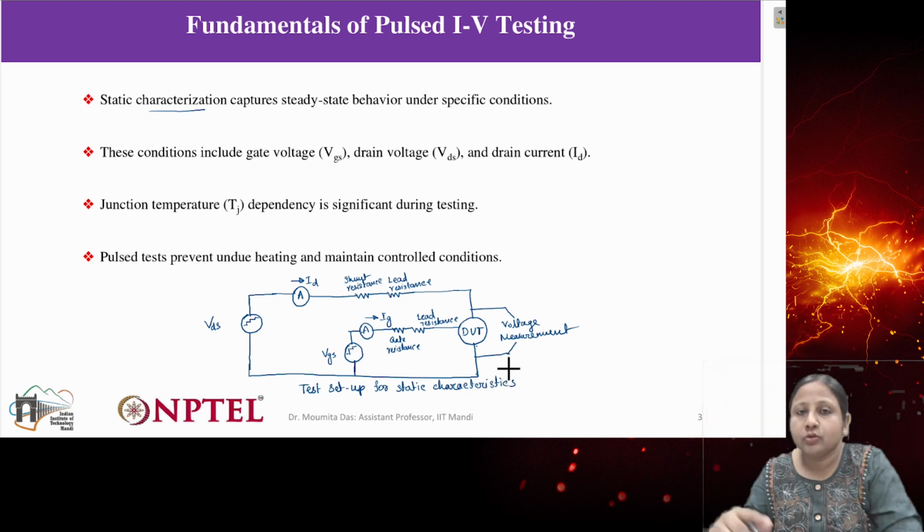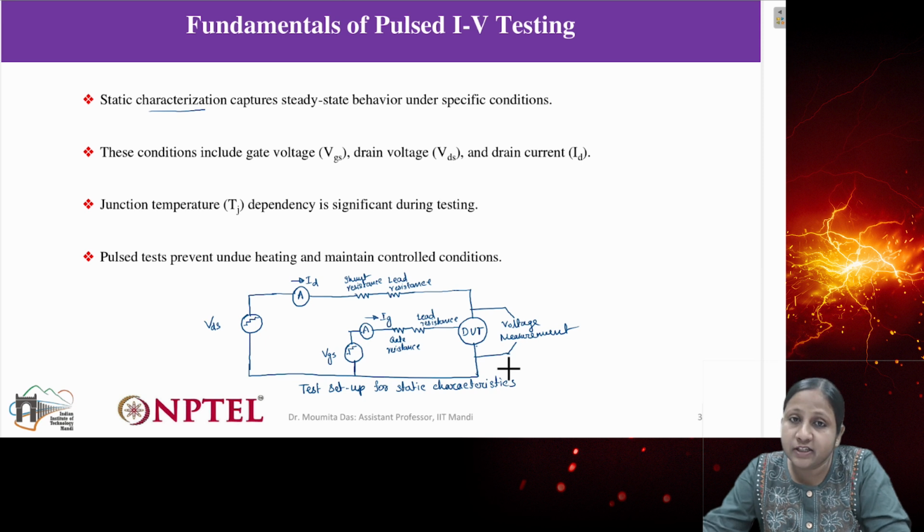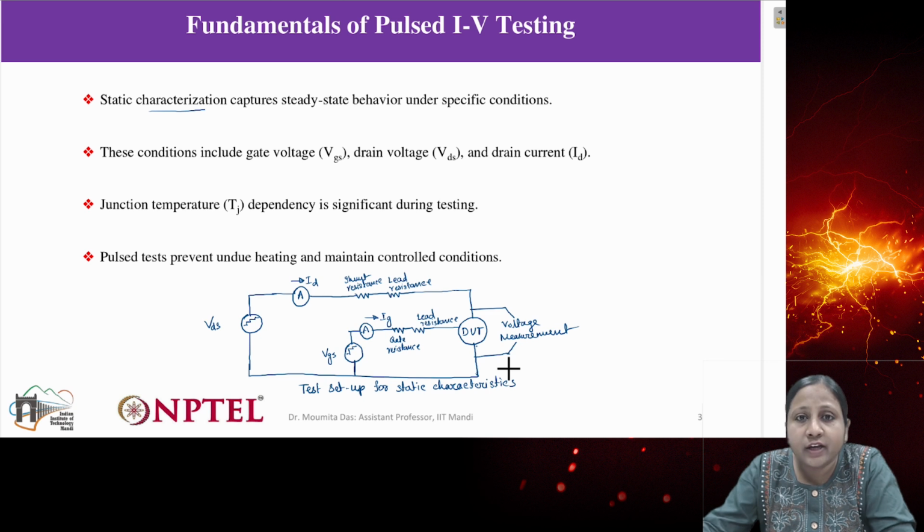Okay, so if you have a curve tracer which is easily accessible, then use the curve tracer. And if you can get a suitable curve tracer for wide bandgap devices, that is wonderful. Otherwise, you can use the same curve tracer which is used for silicon devices and modify it such that you can use it for wide bandgap devices.